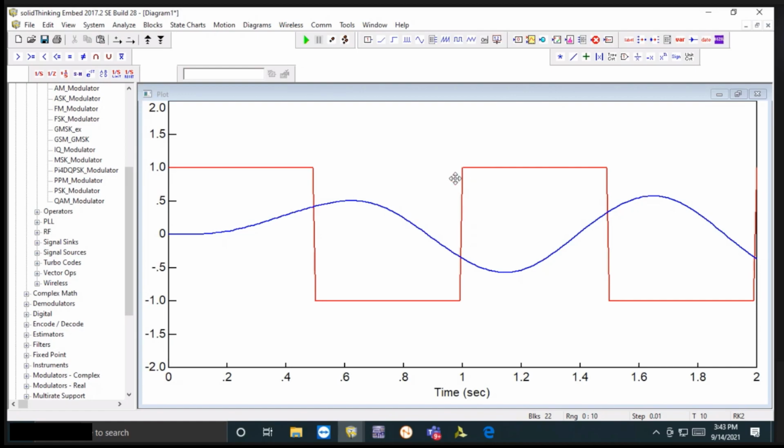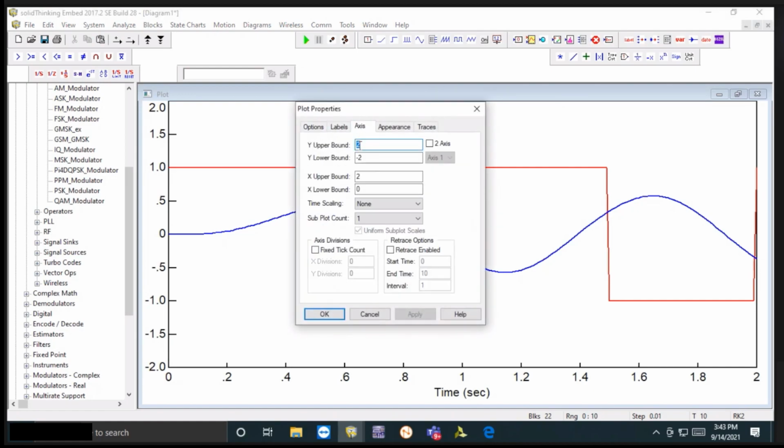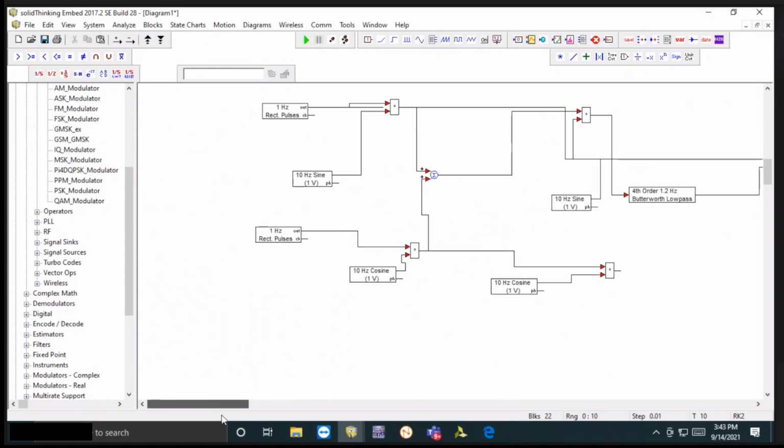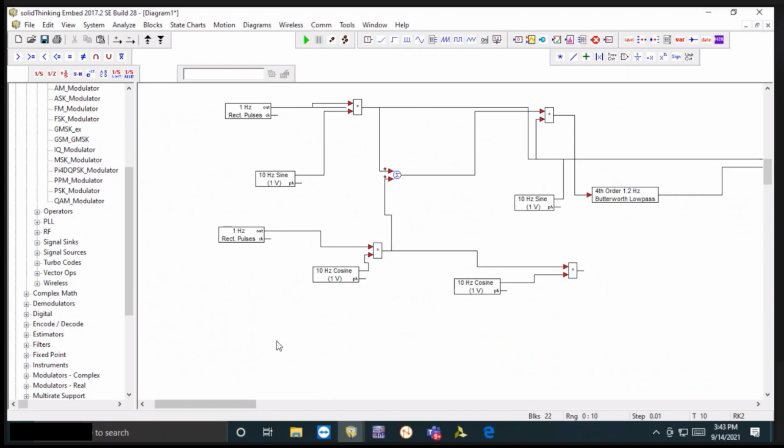The thing is that we can see that we are able to extract our master signal, the same periodic behavior after the demodulation. So what we have done here is take the signal, and on the basis of the odd and even positions, we have divided them into two groups. We modulate them with the same carrier but maintaining a phase shift of 90 degrees. At last, we add them up and then transmit.